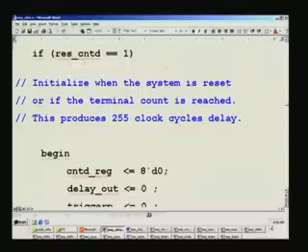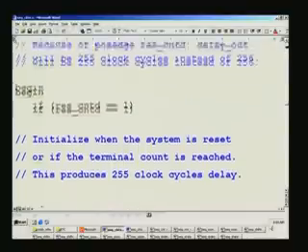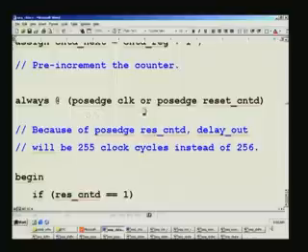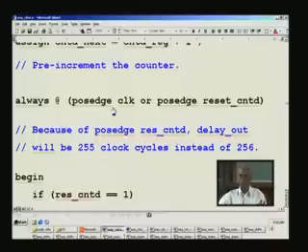So what has happened here is, follow this carefully, this is the crucial thing. We have a positive edge of clock just now arrived which made the counter 255 and immediately following this, within less than a nanosecond or around a nanosecond, this assign statement of reset control D is making it 1. So what happens if that is 1, earlier it was 0.